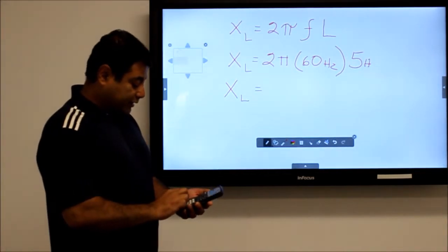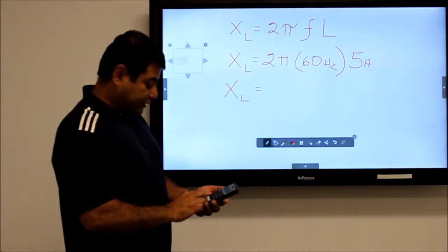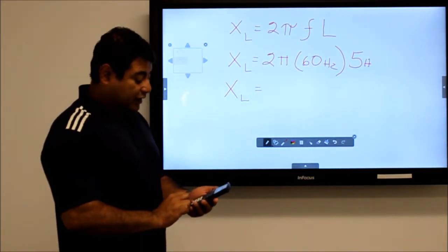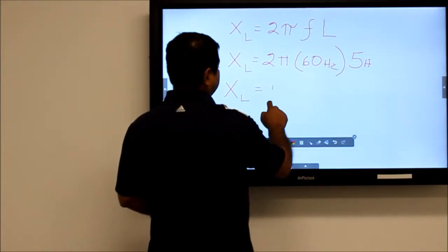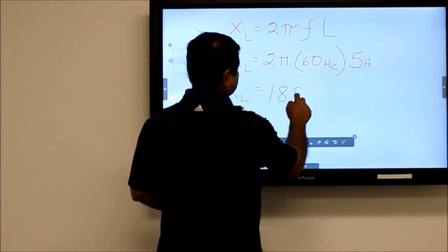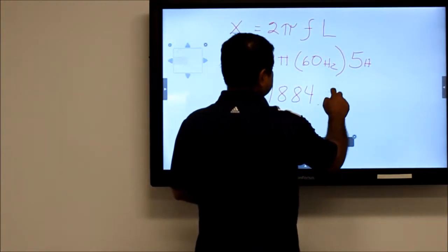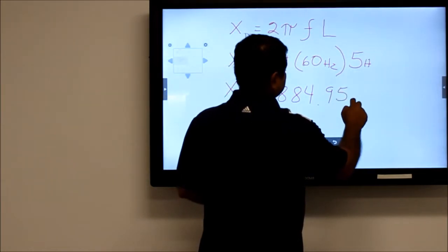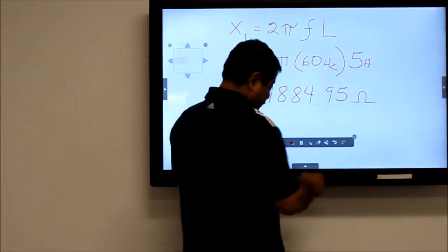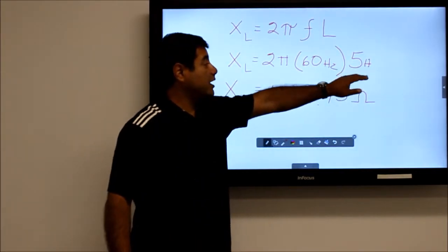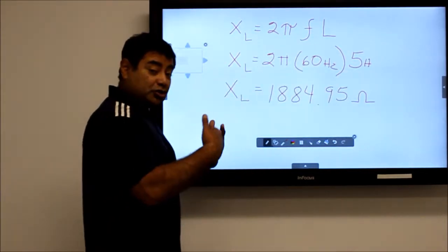It's 2 pi times the 60 hertz times the 5 henries, and I get a value of 1,884.95 ohms.